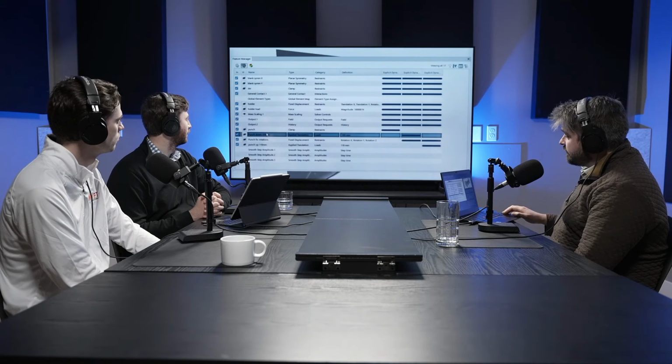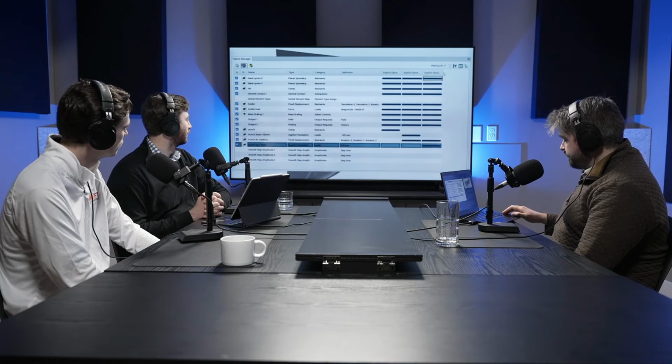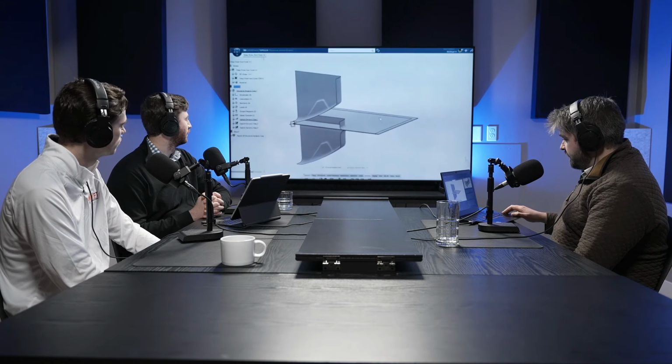So a step implies a simulation. I'm running a simulation at each one of these things. And the step is the step in the manufacturing process. So the first step is the clamp, so I clamp everything down. The next step is the punch. The third step is the removing of the punch. So that would be 3 separate pieces. Yeah. And when we run that, you can see where that lines up. There's our lovely little part right here.